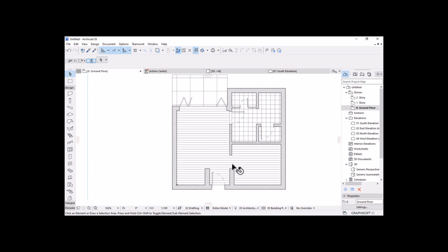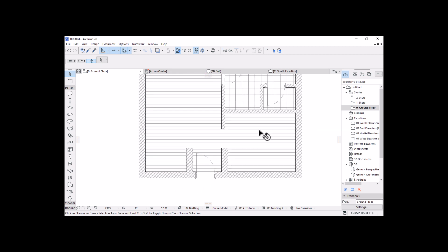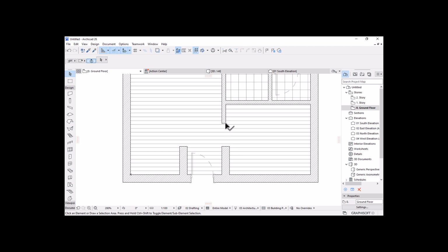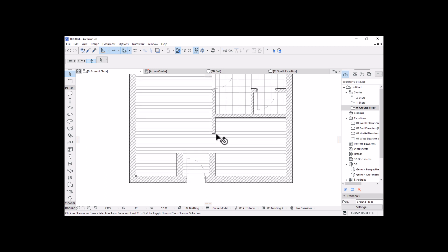Okay, so from here let's move on and do the finish. Let's start with the closet, because I know it requires a lot of input. So I think I need to align this wall with this line. I could select that, then pick this corner, shift and hold, and then click on this line to align. Perfect. So that my cabinetry can be on the same line.